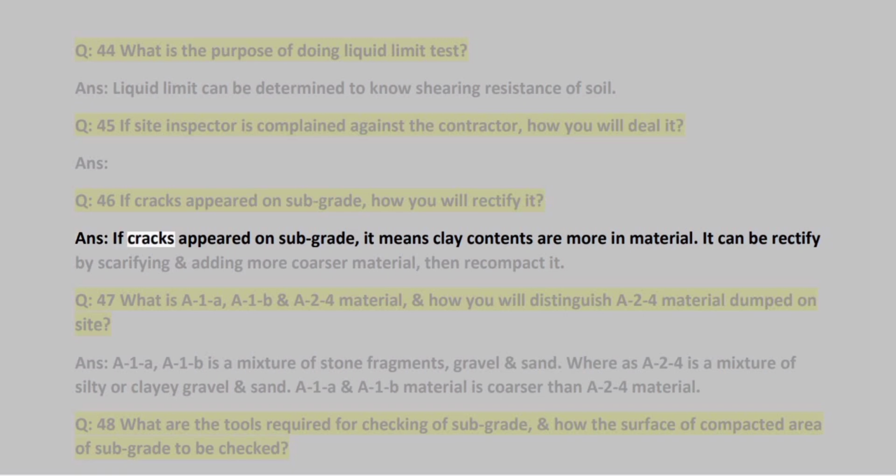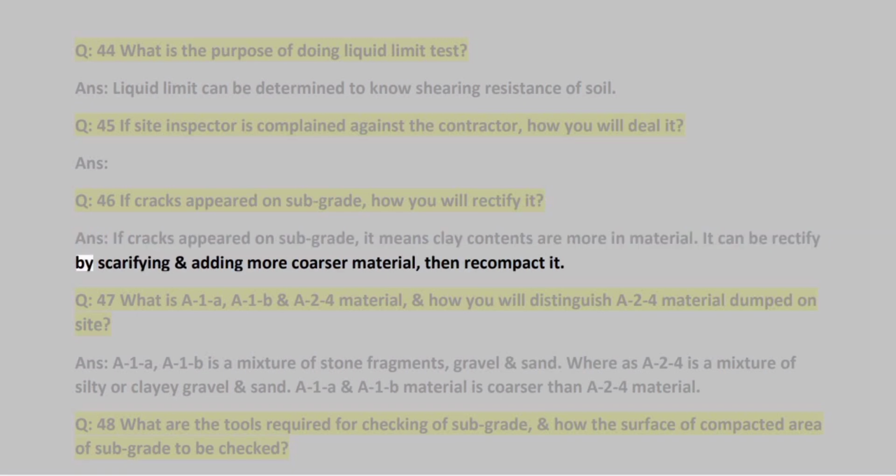Q. 46 If cracks appeared on subgrade, how will you rectify it? ANS, if cracks appeared on subgrade, it means clay contents are more in the material. It can be rectified by scarifying and adding more coarser material, then recompacting it.